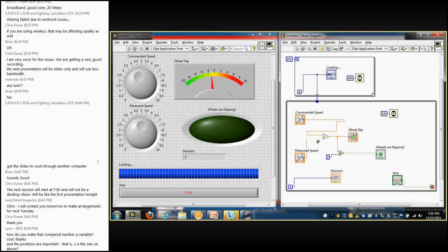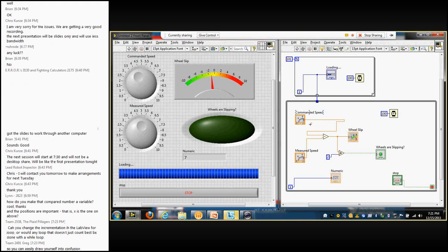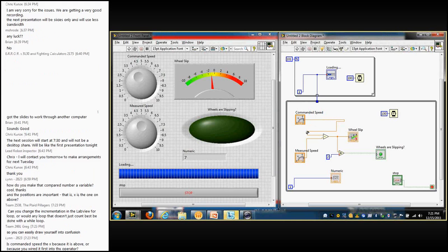I can do just about anything I want. I can have it go under something. I can have it go around something. Data can only be placed on a wire from one location. So on this wire, the data is coming from here. It can go to multiple locations, but data can only be placed on a wire from one location. And that will always determine how data moves through the wire. There is also a shortcut where you can right-click and clean up the wire, and it will reroute it for you in what it considers the most logical way.